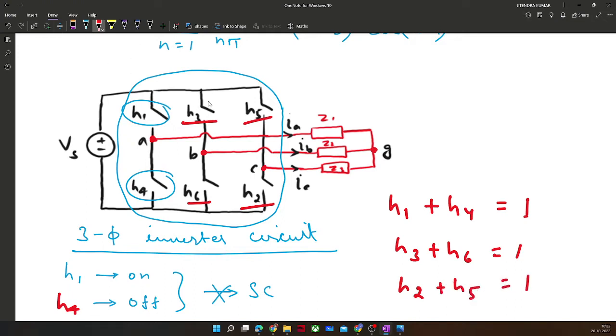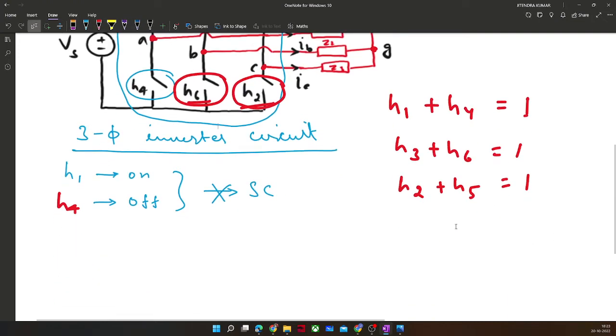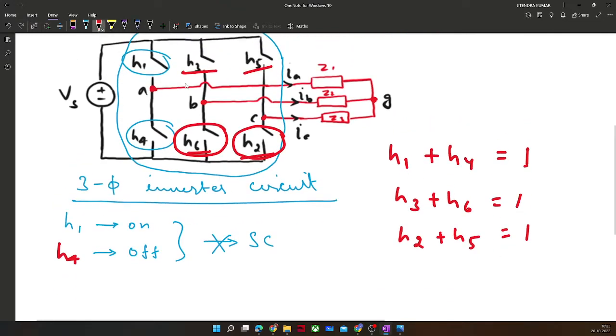So generally, if you recall from 180-degree conduction mode, if you have remembered it, otherwise you just learn it from here freshly. You would know that H1 first conducts for 180 degree, after that H4 conducts for 180 degree, and H1 conducts for 180 degree, in which sometime it will conduct with H6, sometime it will conduct with H2. So this was the scenario there, and let us take this load is connected in a star form.